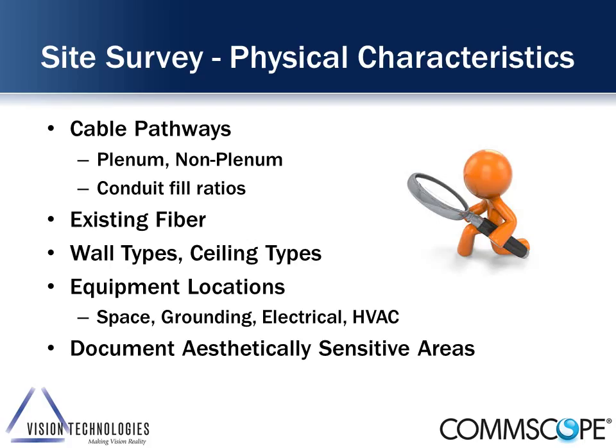Also, with drop ceilings, you need to understand what's above the drop ceiling. In some facilities, there could be 2 to 4 feet of pretty much empty space. In other facilities that I've been to, it's only 2 or 3 inches of space, and it's very crowded up above the drop ceiling tiles. And so you shouldn't make any assumptions. That's what the survey is about, to physically inspect and eliminate assumptions and guesses so you can come up with a more accurate design.